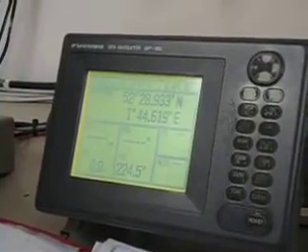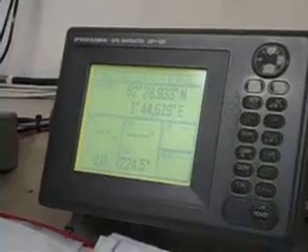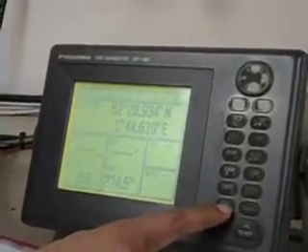Demonstrate how would you reduce the brilliance of the display at night. This is the brilliance. So how do you do that? By pressing the tone button in the normal menu. Tone button. Brilliance is up and down. Minimum brilliance, maximum brilliance. So somewhere in the middle is good.